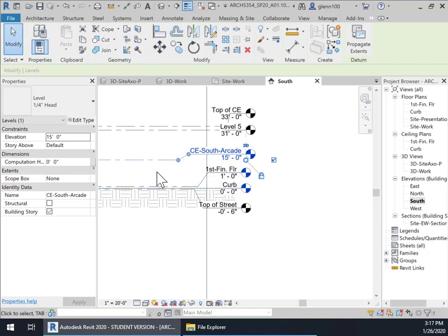As a general rule, most architects, most designers, their first floor is a little taller than norm, usually 16 to 18 feet from floor to floor. And then floors from that point on are, as a general rule, 14 feet floor to floor if you are doing steel. Depending on your spans and whether you're doing concrete, you may be a little bit more than 14 feet. Well, we're going to assume 14 feet.